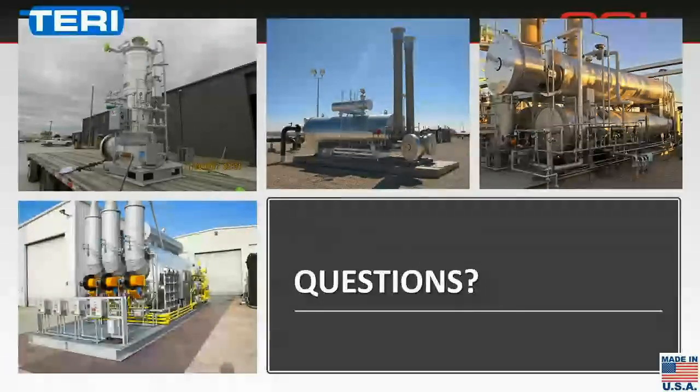So with that, let's go to a final question from Dan. How do higher flux rates affect heater size? Good question, Dan. Higher flux rates, if you recall, you're using a smaller fire tube, and the fire tube defines the length of the heater. So you're able to have a shorter heater. And if you're using a smaller diameter fire tube and a shorter fire tube, that's where you'll start to see your higher flux rates, or the higher heat intensity on your fire tube, which means that you'll have to overfire your burner or use a larger burner.